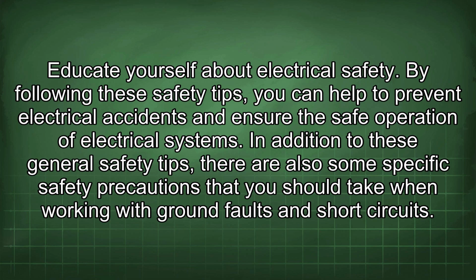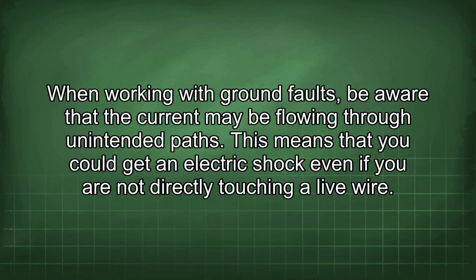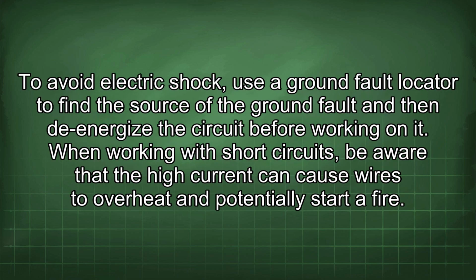In addition to these general safety tips, there are also some specific safety precautions that you should take when working with ground faults and short circuits. When working with ground faults, be aware that the current may be flowing through unintended paths. This means that you could get an electric shock even if you are not directly touching a live wire. To avoid electric shock, use a ground fault locator to find the source of the ground fault and then de-energize the circuit before working on it.